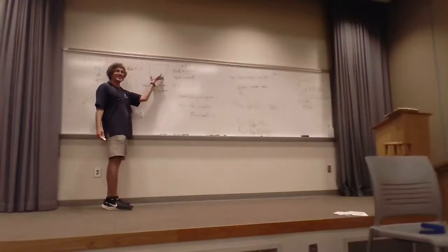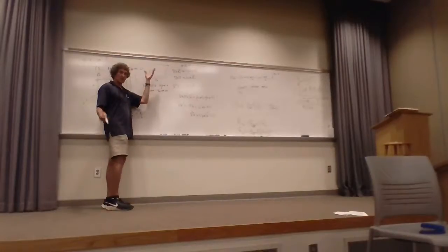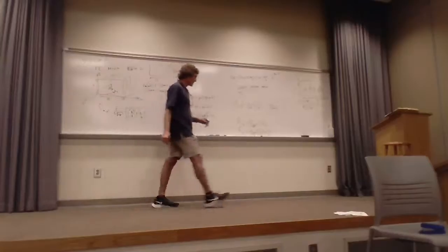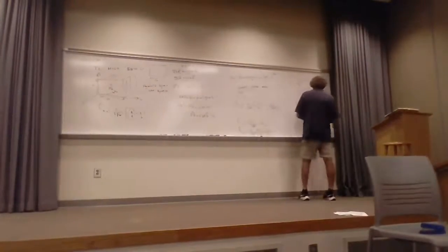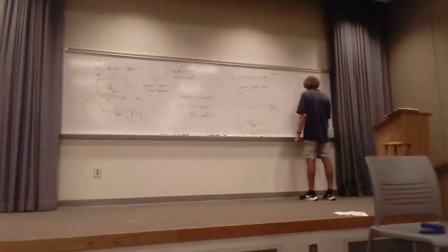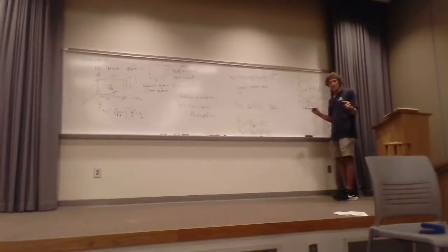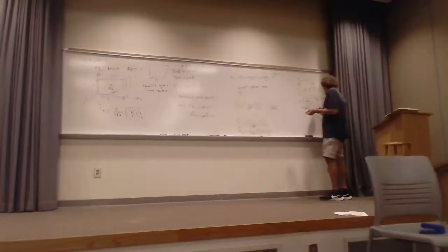Suppose the width of this, just for instance, was 30 centimeters. All right, let's just do this. Talk about this for a second. So if this is 30 centimeters the width, or 30 times 10 to the minus 2 meters, right? I said that was a half wavelength, right? Let's assume it's an air-filled guide. So if it's an air-filled guide, well, what's wavelength in general? We're going free space, but what's wavelength? Isn't it C over F? Right? All right, so it's C over F.